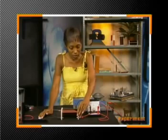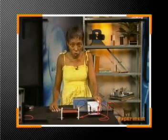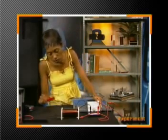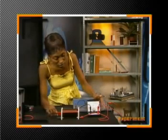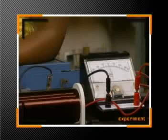The coil is connected to a center zero galvanometer. I'm going to push the north pole end of a strong magnet into the coil. Observe what happens to the needle of the galvanometer. The needle of the center zero galvanometer moves to the right, and then it comes back to zero again.